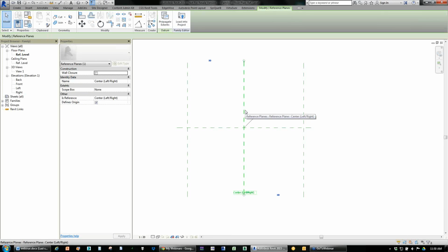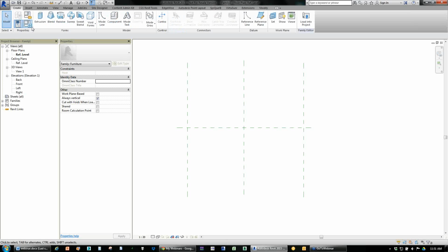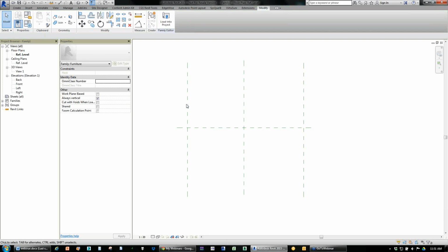So in the case of a family, if we need it to be rescalable inside the project, like a door or a window or so forth, then we need to make it parametric, rescalable. And we'll do that in a sec. And the last piece is the flesh, and that's the geometry. So the geometry actually hangs off the skeleton and then gets driven by these muscles, by these special dimensions that we'll create in a sec.